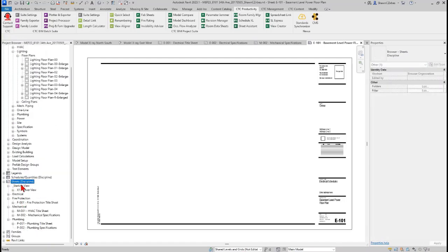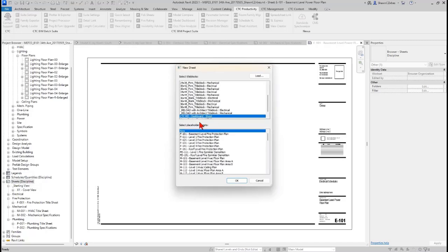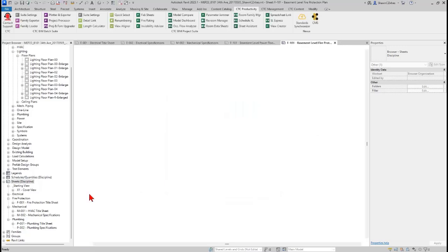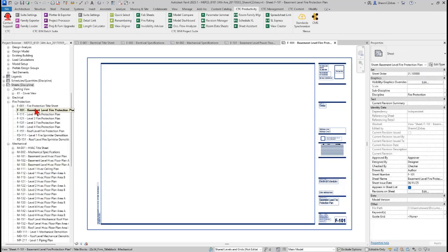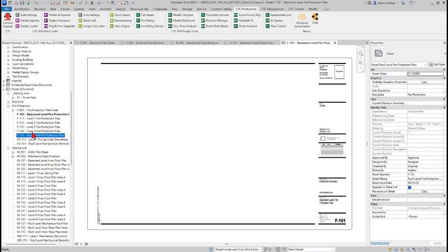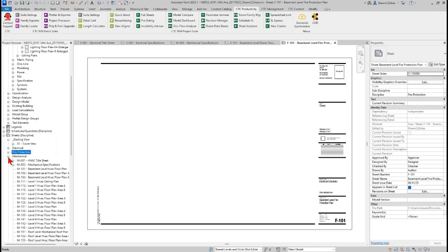So there's all my electrical sheets. Now, if I want to do the rest of my fire protection, mechanical, plumbing, they're all going to use that mechanical title block. So new sheet here, once again, 22 by 34 title block mechanical in this case, and I'll just grab all the rest of my sheets that are here in my placeholder list and tell it to generate them. Because of the properties that are pre-specified on those placeholders, because of how this is made, it knows to group in the correct area. It knows for my actual sheets list to sort them based on the grouping they're supposed to be in, because every one of these knows over here, sheet order 23.1. It knows that over here, 21.1, because of the settings that were in my file. So this makes this really easy for me to get all my sheets ready to rip pretty fast, right?